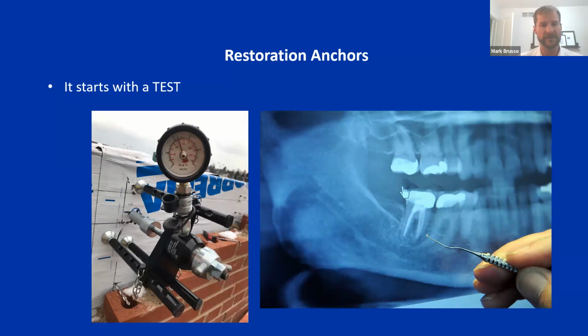And so what we do in restoration is often test first before we come up with a design. What's involved oftentimes is doing a pull test on the backup with some of the anchors and ties that we're using in restoration. And it's not a complex thing. It's mainly applying an actual load with a test device, which will give you a value in kilonewtons, the metric unit of force. Those familiar with Newton's law, 1 Newton is equivalent approximately to holding 1 apple a meter in the air.